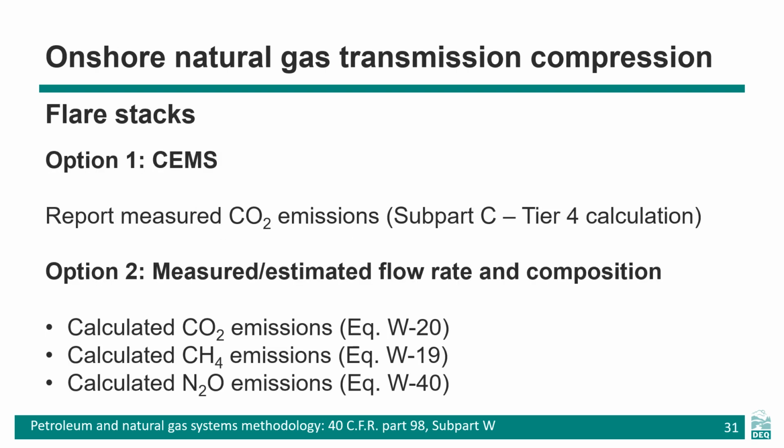Flare stack emissions are calculated based on what type of monitoring devices are installed on the flare stack. If a SEMS is installed to measure flow and CO2 emissions, then this value should be reported using a Tier 4 calculation methodology from Subpart C. Otherwise, emissions for CO2, CH4, and N2O should be calculated using the equation shown here.